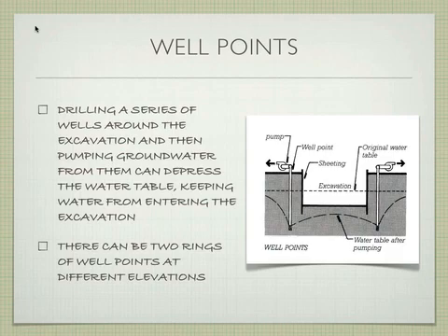Just recognize that you can have these, but the same problems still exist with these well pumps. You still have that water. You still have to be able to get rid of it if it's toxic. If it's coming from a well like this, it's more likely to be less toxic than if you're pumping it out of a sump pump because you've got construction debris and mud falling into the sump pump, as opposed to this, which is theoretically a relatively clean water source. But again, it depends on where the building is.